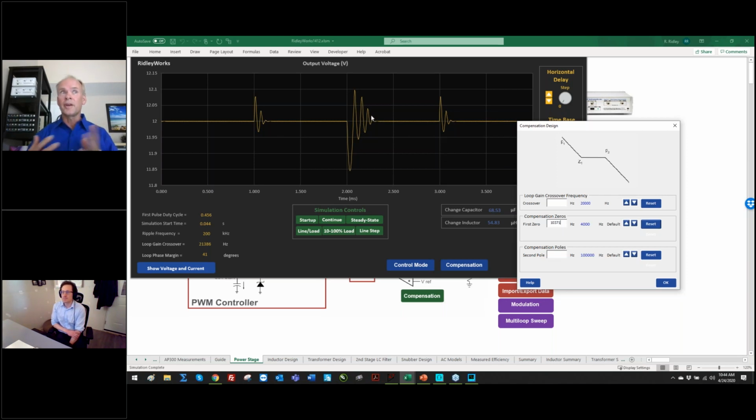So I'll see lots of app notes say, well, we can do 30-degree phase margin, it's fine. We can do 23 degrees phase margin, it's fine. The overshoot here won't change a lot, but you don't want this to start happening. And then, of course, if we start going too far with this, let's bring this pole down. And of course, you get this weird thing where the phase margin doesn't quite correspond to when the oscillations come in, because you get large signal oscillations as well as small signal oscillations, all right? Send those back to our design point.